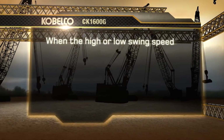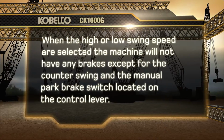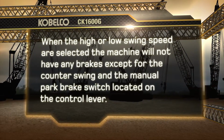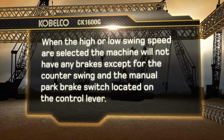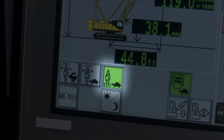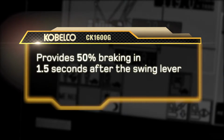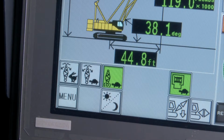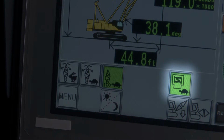When the high or low swing speed are selected, the machine will not have any brakes except for the counter swing and the manual park brake switch located on the control lever. And the third icon is the swing brake. In low speed swing, this setting provides 50% braking in 1.5 seconds after the swing lever has been in the neutral position. These are followed by the work mode select icon.